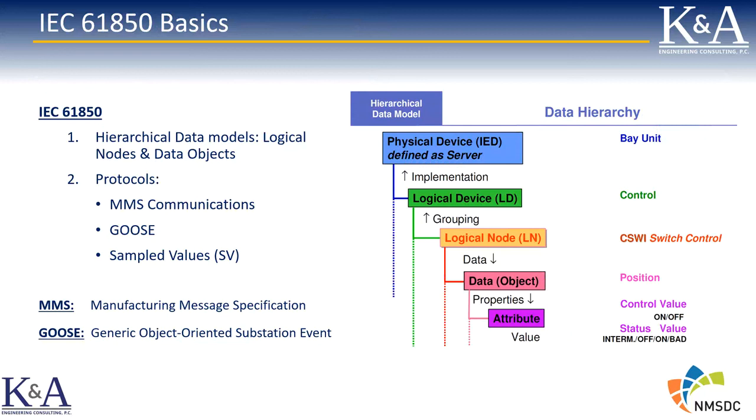This doesn't happen in IEC 61850 because in the data models, the values are all self-naming and self-referencing. The values are given a path name that completely defines the position of the point within the station and its function as well.